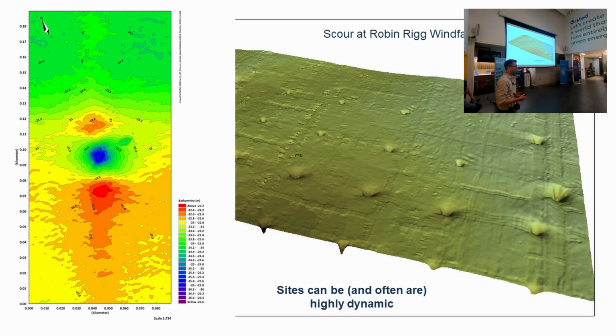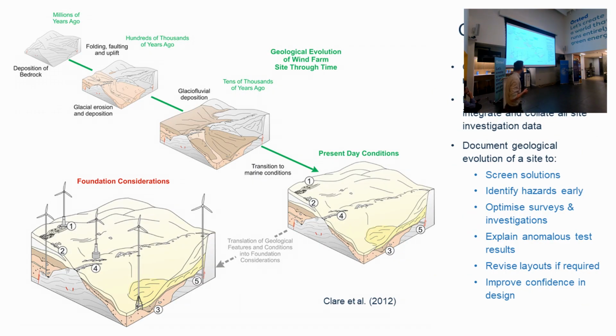So this ground model needs to be updated. For oil and gas developments, ground models are being updated to include decommissioning stages as well. So it provides you with an opportunity to manage and make sense of large data volumes, just some more evidence of scour and then deposition around the monopile. As I said, it's not really showing too much of the nuts and bolts, but hopefully it's an overview of the philosophy behind the ground model, why it's important to respect the geology, because that sets up the site as it is. But there's a need to communicate that geology to engineers, and for engineers to also communicate what's important, what represents a constraint, what horizons might actually be appropriate to pick, rather than just the easiest ones.